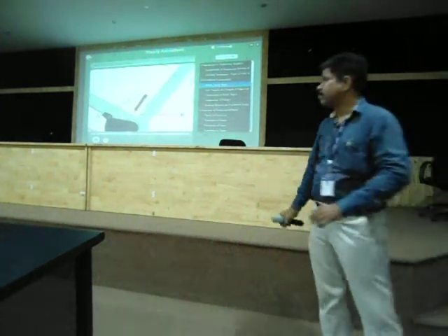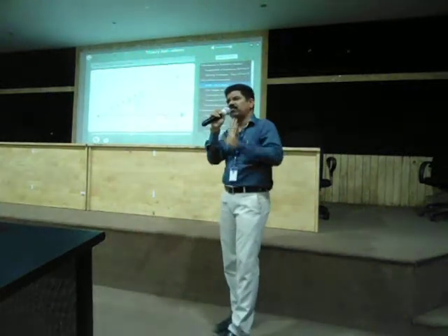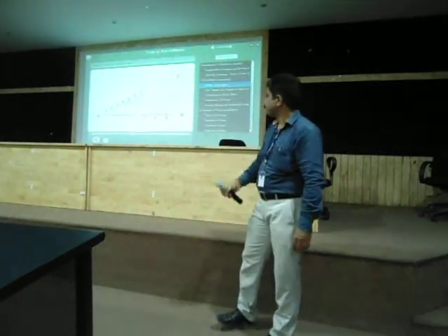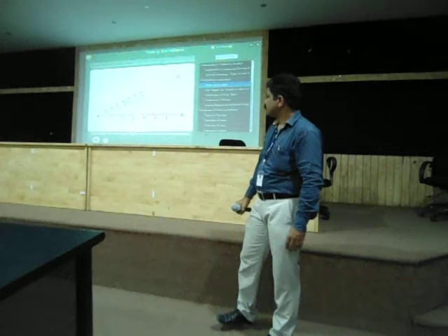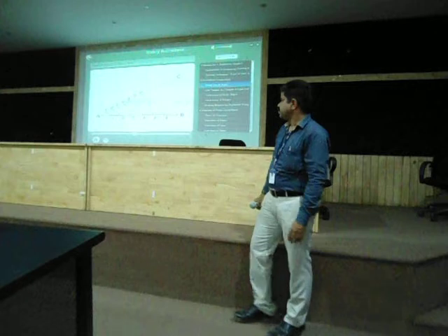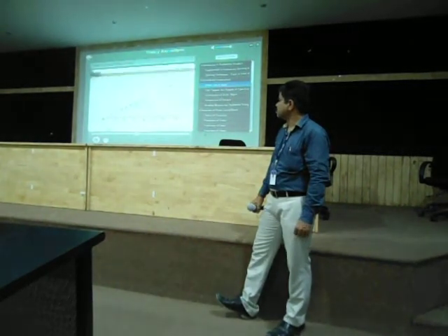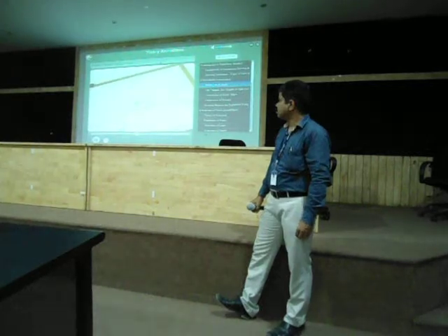Draw lines parallel to 7 dash B. How to join the line, that is also important. A drafter will be helpful for you people. Then 4, 3, 2 and 1 respectively. 7 will be the last, B. The line AB has been divided into 7 equal parts. It was easy, isn't it?